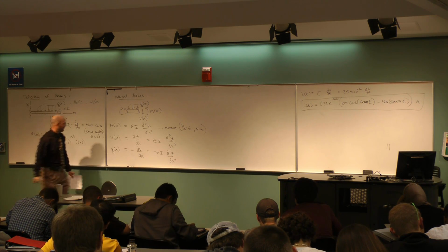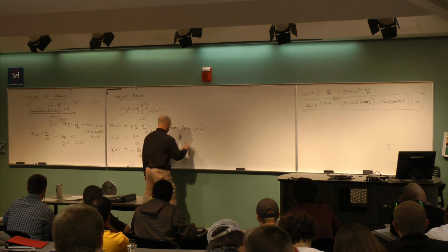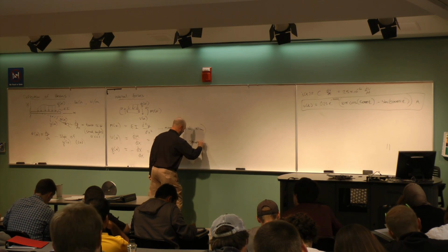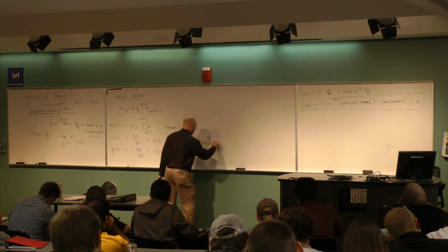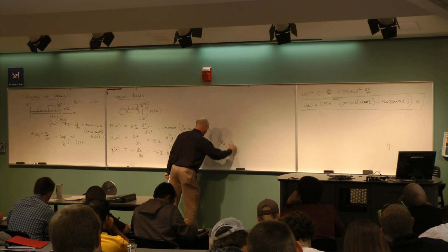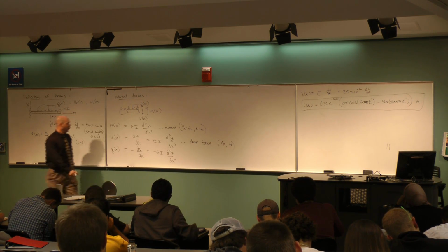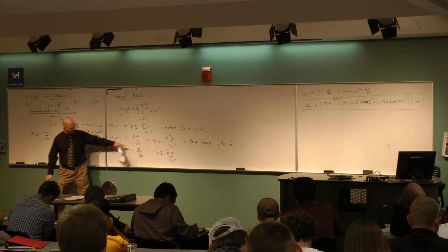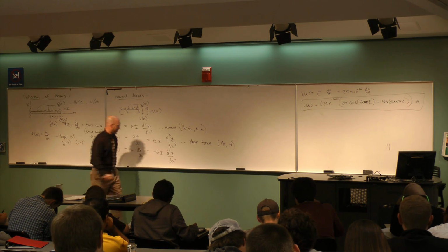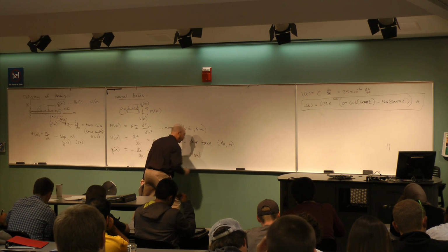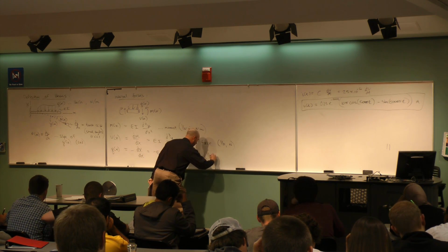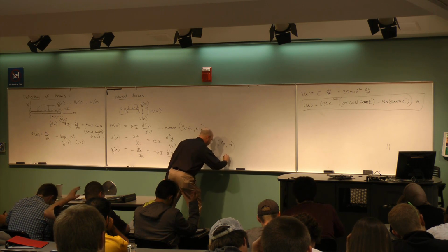Okay, and so the units on each of these, V is the shear force, right? This is the shear force. And so the units of force would be either pounds or newtons, right? And then finally Q is one more derivative, right? So force per unit length. And that's how I get distributed load. So this is the load, again, pounds per inch or Newton per meter.